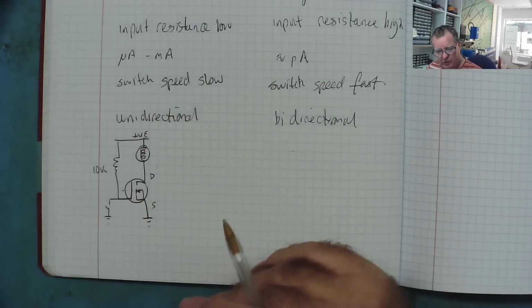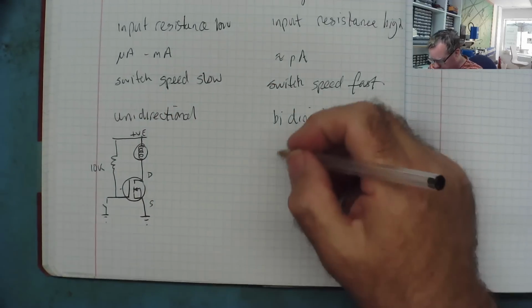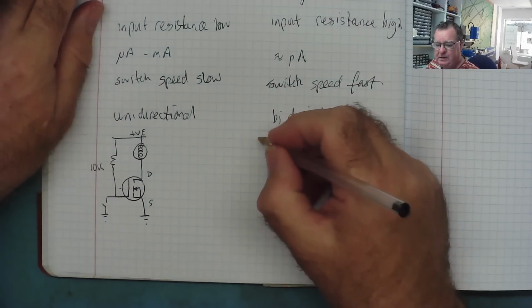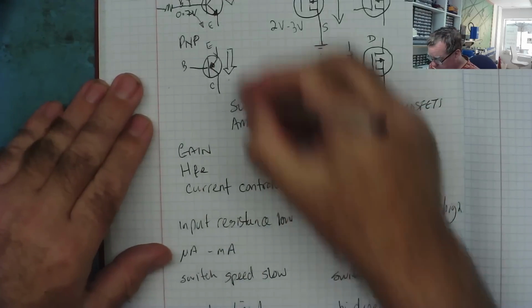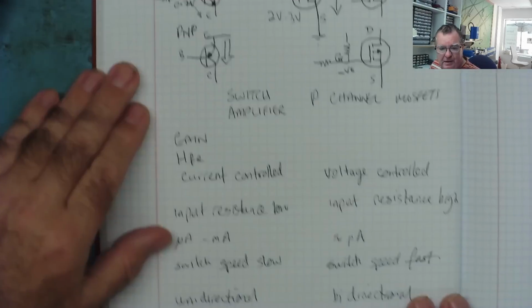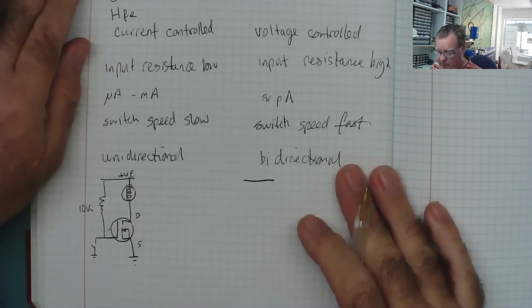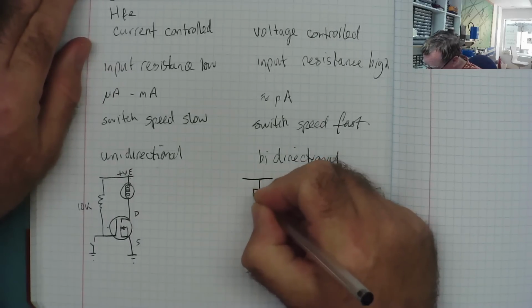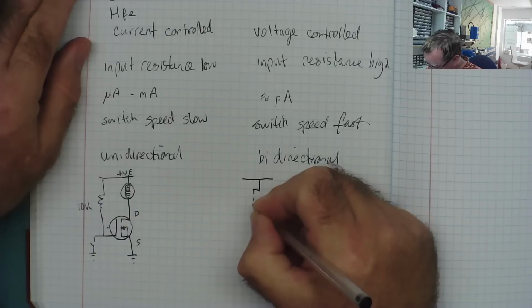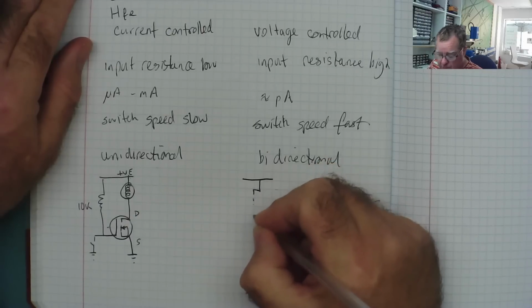And that's quite intuitive. With the P-channel MOSFET, we need to think of it like this. So just like the PNP transistor tends to be used this way up with a positive voltage rail here, this is much the same. So we now have our P-channel MOSFET. We'll put the load, no, we'll put it here.